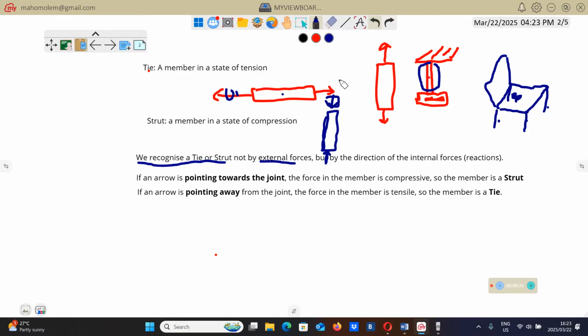The reason your hands won't be moving is because as the hands apply external force on this thing, the material of that pen will apply force on my hand in the opposite direction. We call this a reaction force or the internal force. So the material of that pen is going to pull back, it's going to react. As you try to stretch it, it will resist and develop an internal force. Those internal forces will act in this direction.